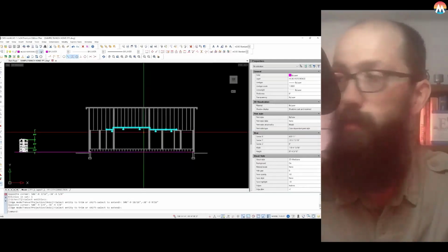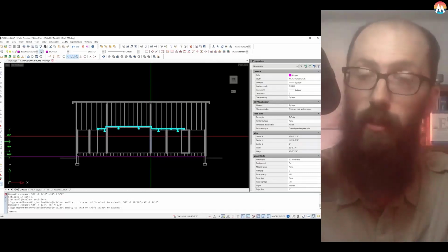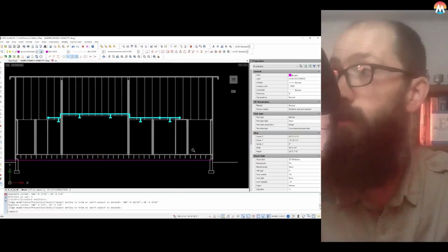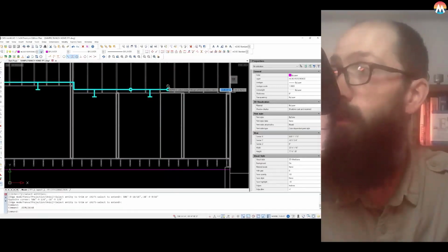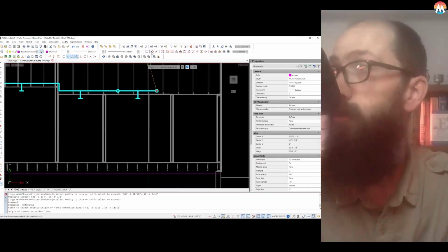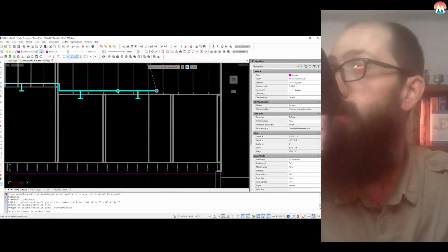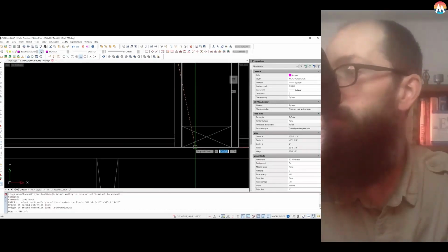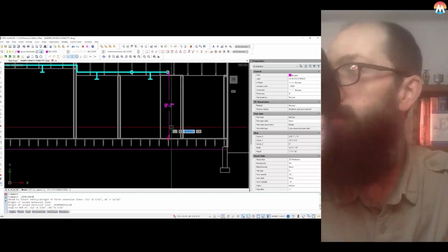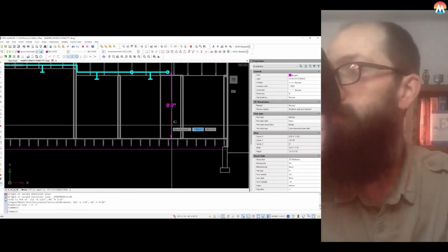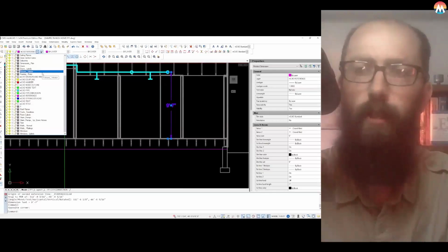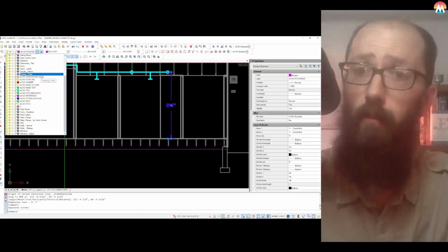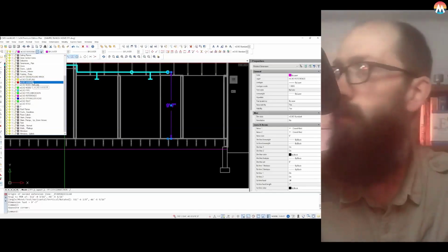Now, the most important information is actually not on here yet. What is useful for the plans reviewer is to have the elevation of this piping off of the finished floor, usually. Because when I say finished floor, I really mean this, not the floor that has whatever your finish is, like wood, but the finished subfloor.